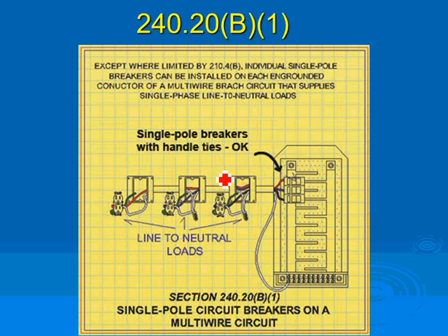Now, recommendation, being an engineer, the only way you should think of this is really if you're tying line to neutral loads, like lighting loads, receptacle loads, equipment loads that are line to neutral. Every time you tie line to line equipment, like 208 or 480 or 240, you should use two pole circuit breakers. It's more reliable, trips better, and so forth. But you are allowed to put two single pole circuit breakers on a 240 load, as well as a 208.